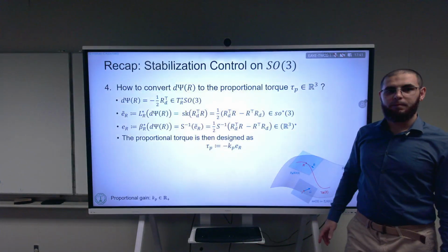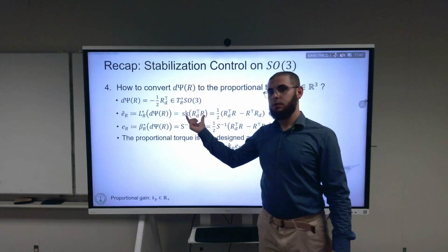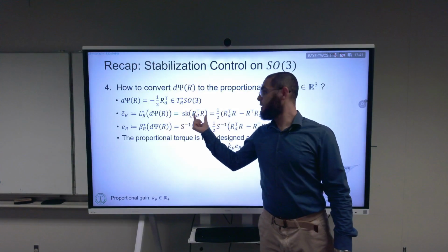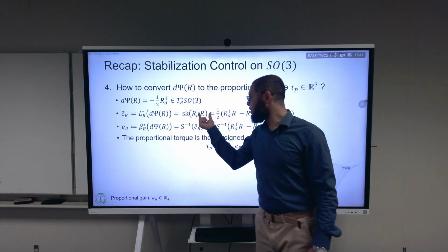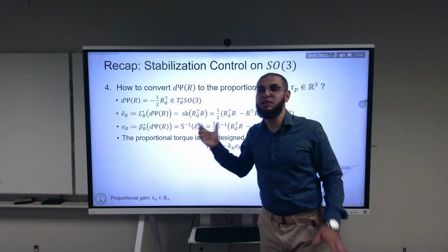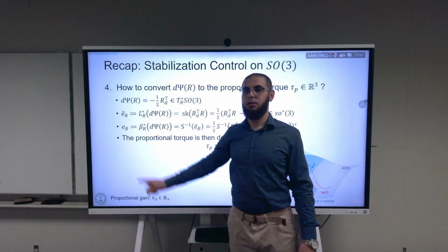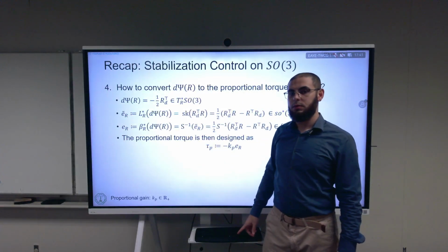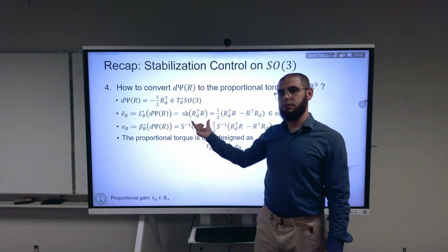Can we get R_d^T R without the skew-symmetric form from the E tilde? This term, without doing skew-symmetrization, it will not be valid. That's what we discussed last time, that R desired transpose R by itself is not skew-symmetric. So I cannot equate it to something that's skew-symmetric. We change the R_d^T R to a skew-symmetric form. That's right, this equation.